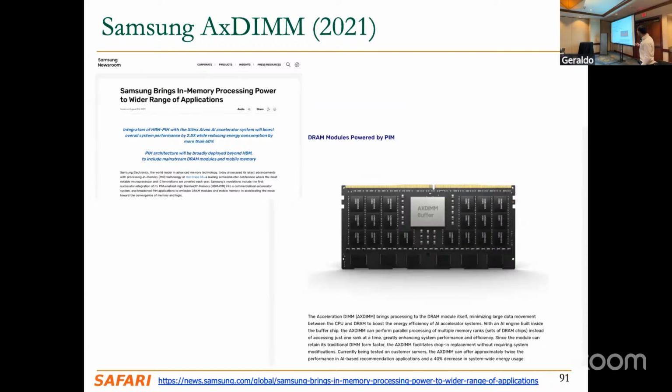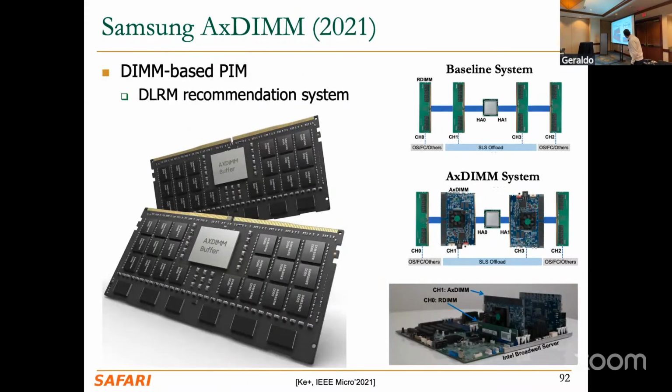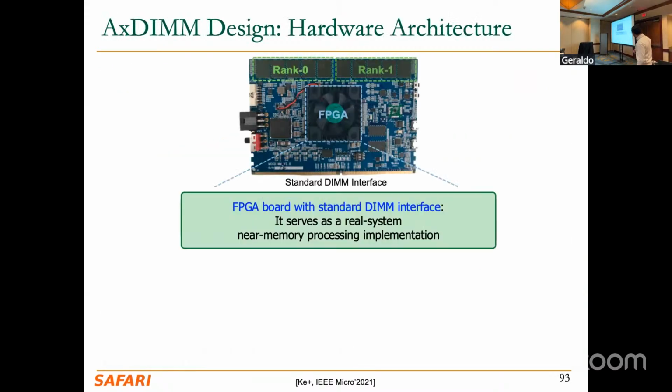Samsung in 2021 had this paper where they have this FPGA, this DRAM, and together with that we have this IXDIMM buffer in the middle, which is basically an FPGA-based system where we can reconfigure the logic to do different operations. Initially they proposed this for recommendation systems, and I have an overview of the design here.